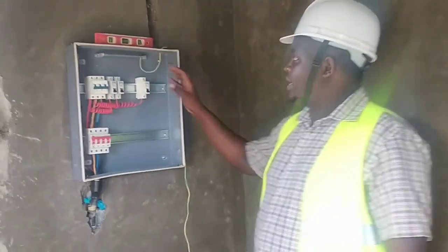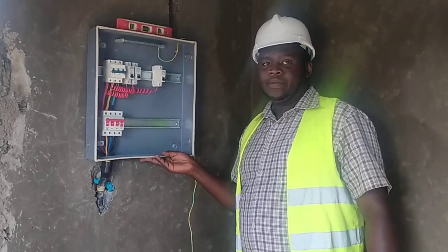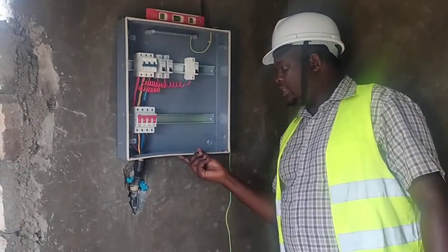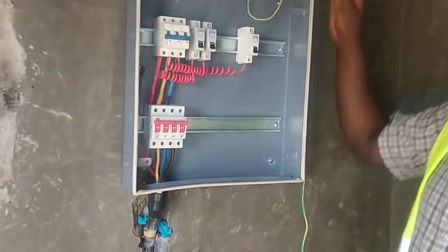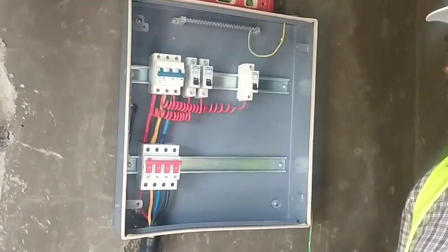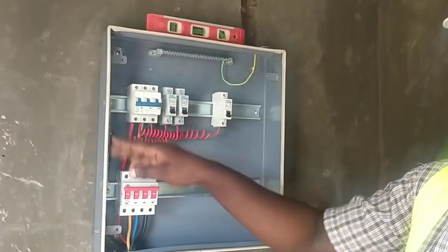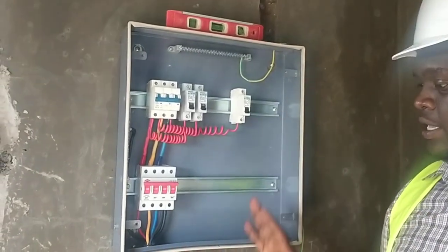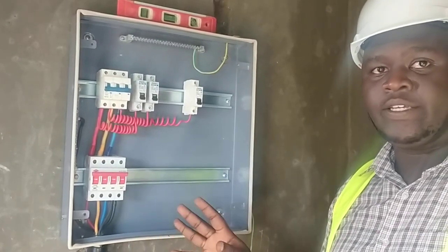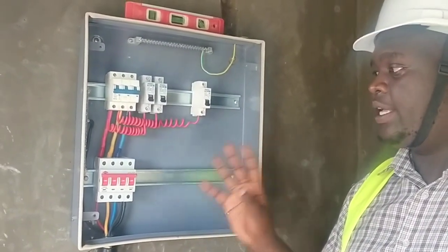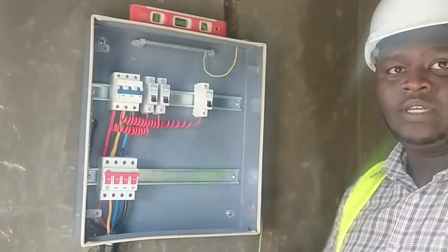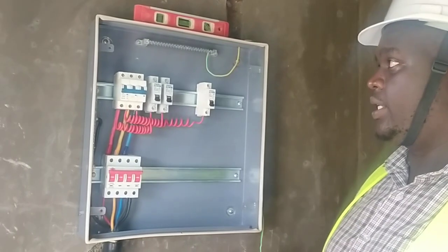So I want us to look at the parts of our distribution board. Number one, we have the main mechanical frame. You have these holes so that you can get your piping or wiring system going through. You can also use a knockout system. Inside it, you have these terminals. So this is a warning: in my case, this one has not been terminated, so this is a dead circuit. Whenever you are doing any electrical termination, please don't do what I'm doing, because I'm working on a dead circuit, lest you get electrocuted.